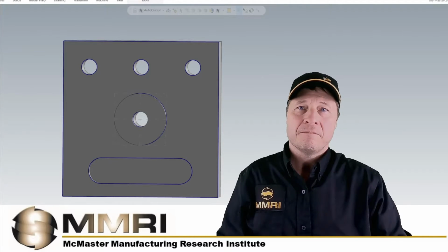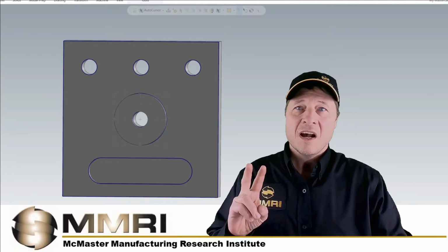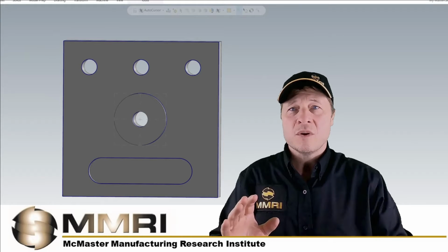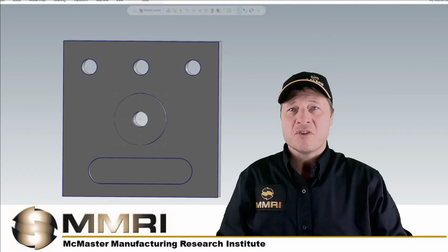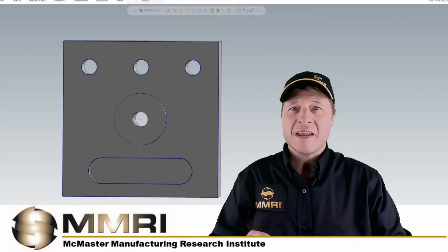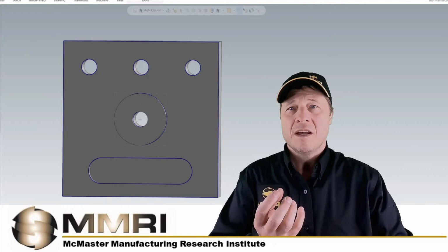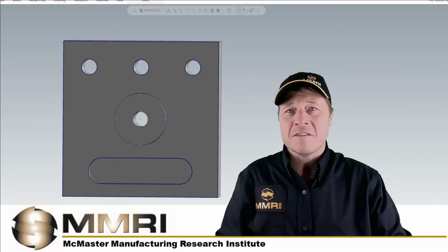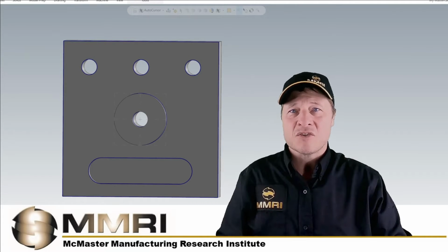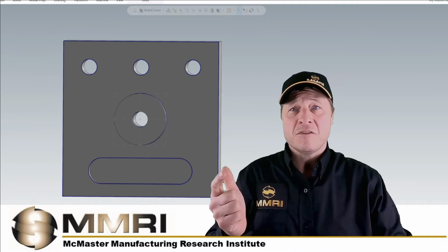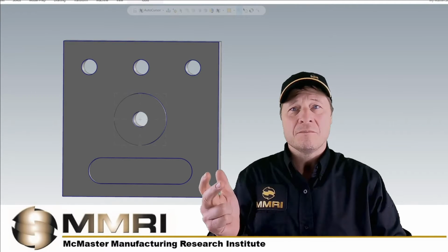There are two systems of arranging views to describe a part. We are only going to consider third angle projection. Like first angle projection, third angle projection is a way of positioning views. And now typically, only three views of an object are required to accurately describe the shape of that object. Those three views are the top view, the front view, and the right side view.